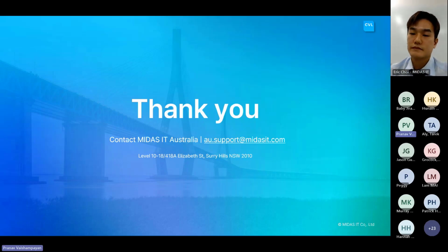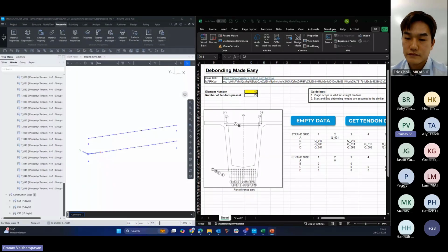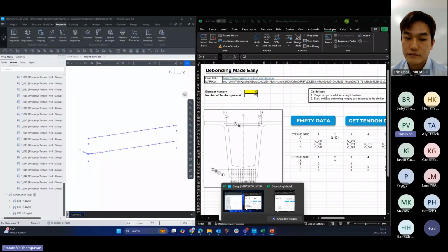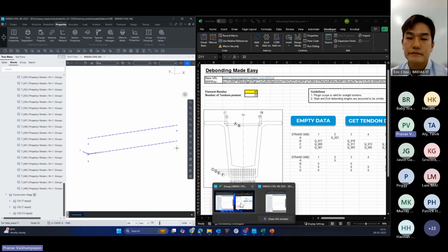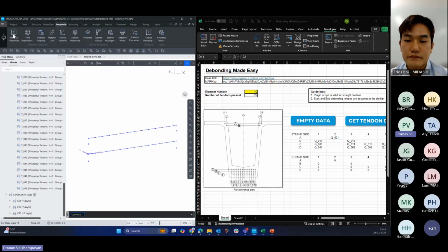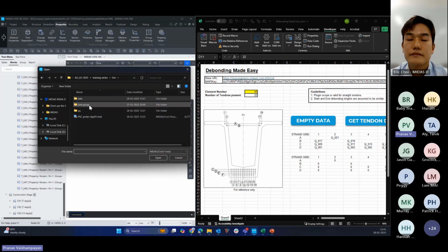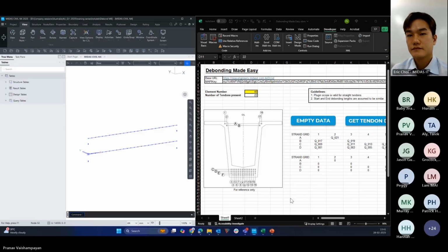So we can also use it for varying ground level, but the scope of this current plugin is fixed to a single reference node. But if your force deformation functions at the respective depths are the same, then you can choose a different reference node, arrange your force deformation functions according to that node, and even if the corresponding nodes are at variable depths, it is possible. Let me explain what I'm trying to convey.